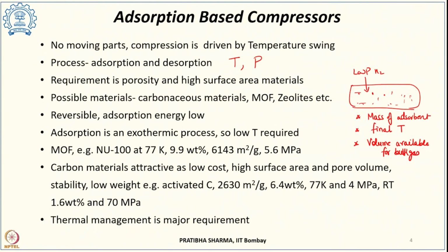If the heat produced during adsorption is not removed, it will increase the temperature of the bed, which will reduce the rate of adsorption, and we will not get good efficiencies.